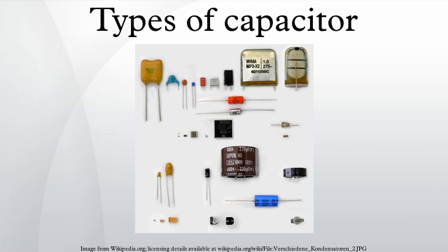The smallest discrete capacitor, for instance, is a 01005 chip capacitor with a dimension of only 0.4 mm by 0.2 mm. The construction of ceramic multi-layer capacitors with mostly alternating layers results in single capacitors connected in parallel. This configuration increases capacitance and decreases all losses and parasitic inductances. Ceramic capacitors are well suited for high frequencies and high current pulse loads. Because the thickness of the ceramic dielectric layer can be easily controlled and produced by the desired application voltage, ceramic capacitors are available with rated voltages up to the 30 kV range.